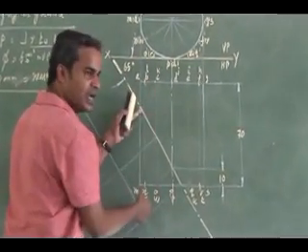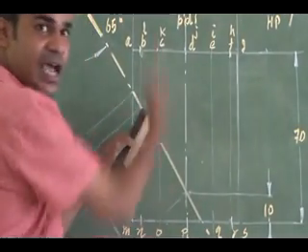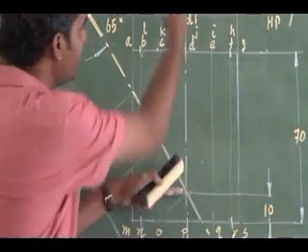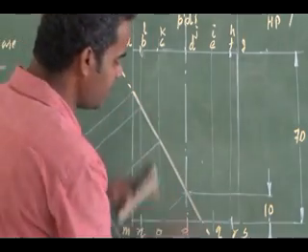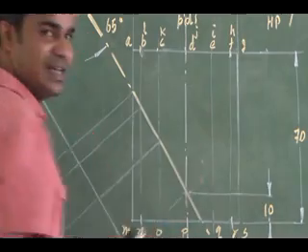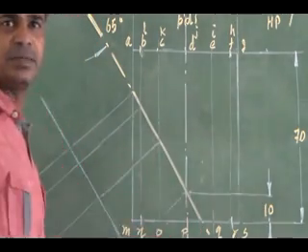Next to that I will have two generators, one visible, one hidden. Then next I will have two generators, one visible and another one hidden. Here in the middle also I have two generators, one visible and one hidden. Then immediately next it is hidden. In this orientation it doesn't cut another generator. It cuts the base, the nearest base.